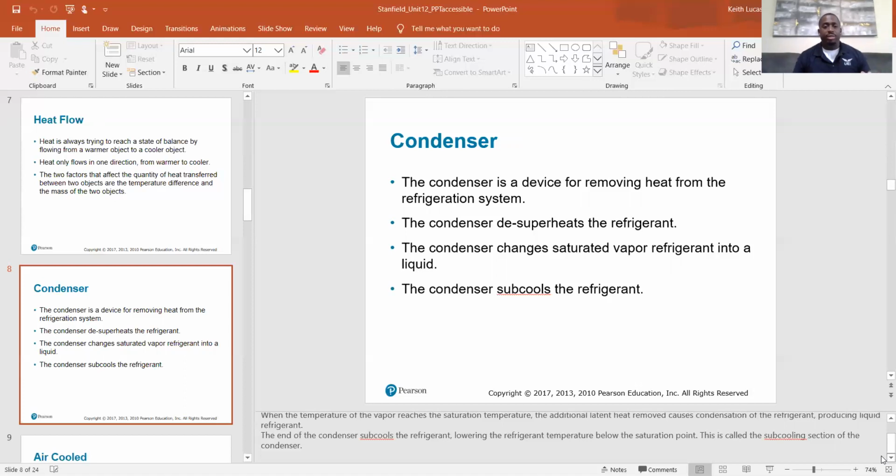So the condenser is like a radiator. It's just one big coil, one big copper coil with these aluminum fins that are there to direct the airflow across the coils and promote good heat transfer. So they described it in three sections, but it's one coil. It's not physically broken into sections, but they're just giving you a guideline.